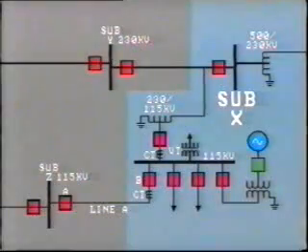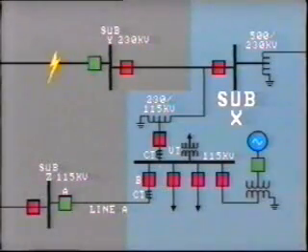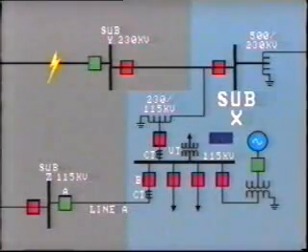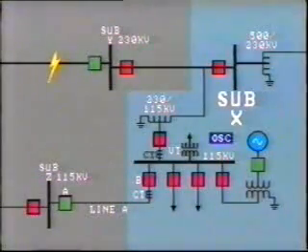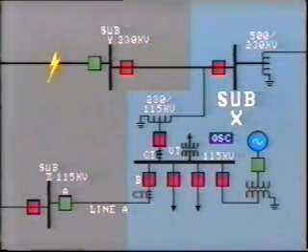Breaker A at 115 kV substation Z trips for a remote fault on the 230 kV system. With the help of the oscillographs located in substation X, we were able to spot the problem and correct it. In substation X, the oscillograms monitor the transformer breaker's A-phase current and the zero sequence residual current. Also monitored are the 115 kV bus voltages in all three phases, as well as A-phase and residual current for breaker B connecting to substation Z.